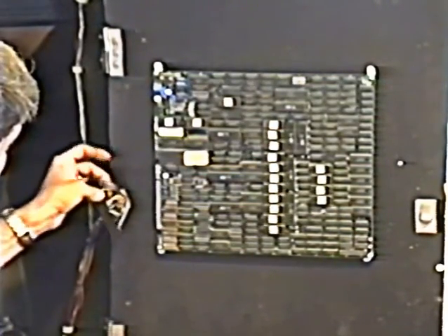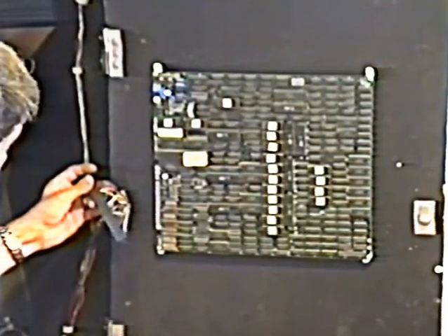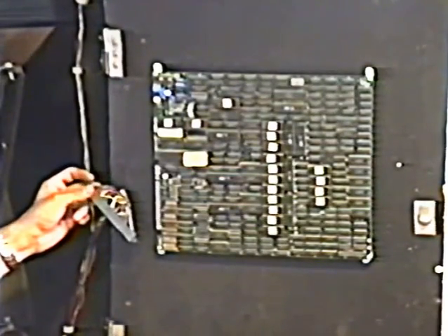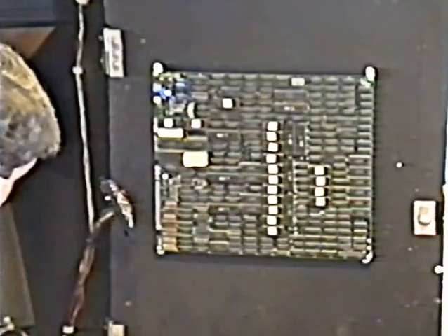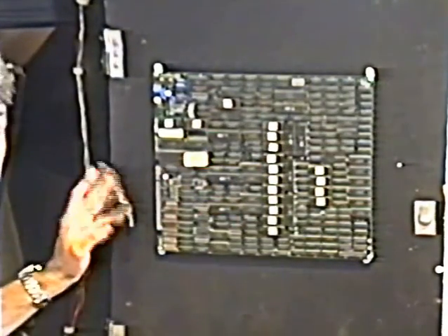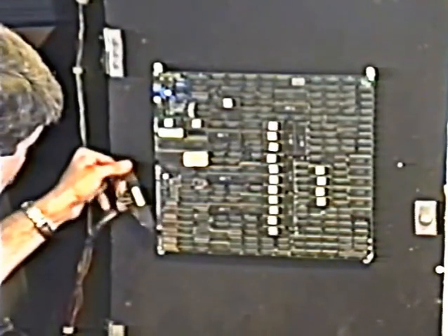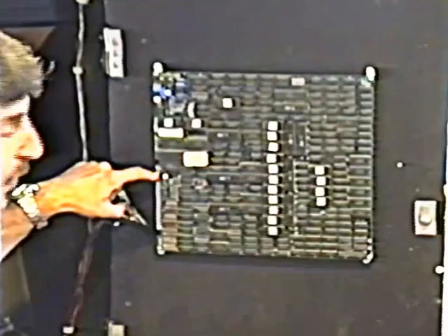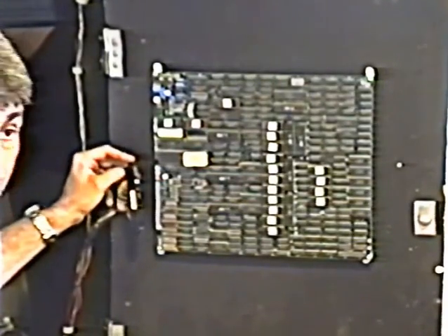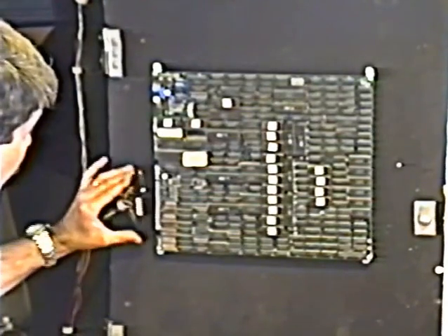You'll notice that they've doubled up on the wires here. In fact, there's 4 ground wires and 4 plus 5 volt wires. That's because by the time the current gets out of the power supply to the board, you can lose some voltage there. The more wires you have, the less voltage you'll lose. Plus, if you just run one wire, you'll probably burn the pin on the board, and you'll burn the pin on the connector. We'll talk more about those pins in just a little bit. So they run multiple wires.